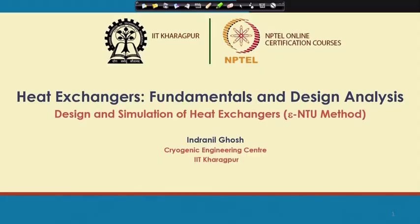This lecture is in continuation to our earlier discussion on design and simulation of heat exchangers. Today, we are going to talk about the epsilon-NTU method. Last time, we talked about the LMTD technique. Now, here we are finding two new terms: one is epsilon, or the effectiveness of the heat exchanger, and the other is the number of transfer units, or in abbreviated form, the NTU.